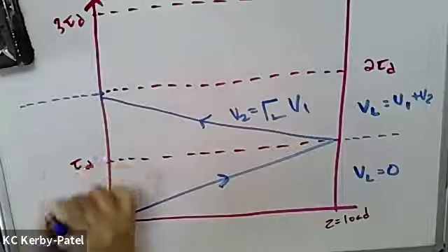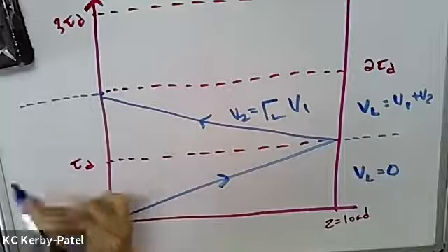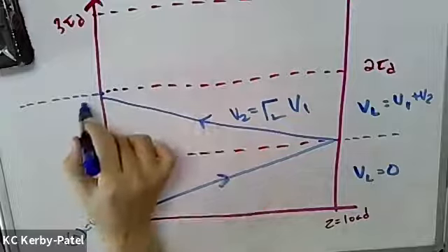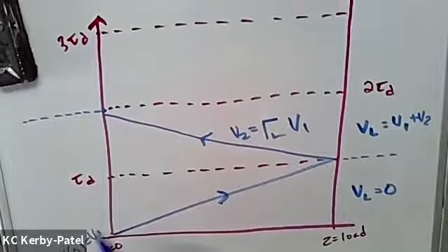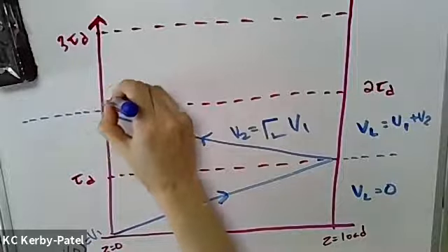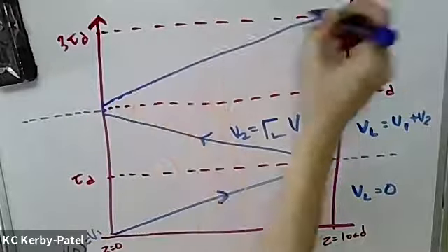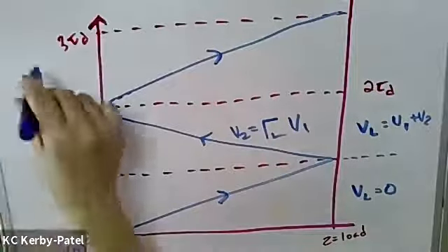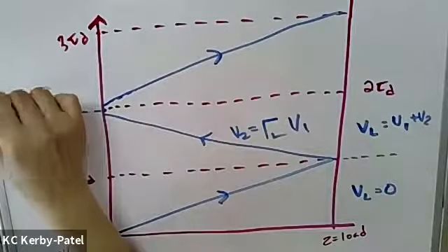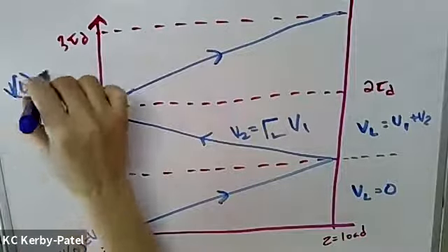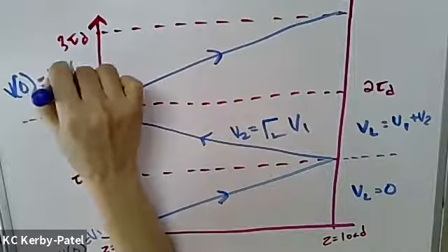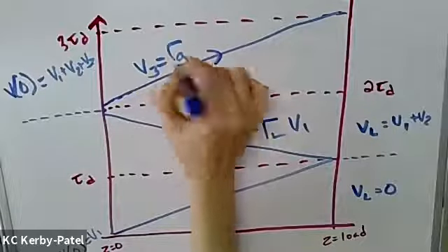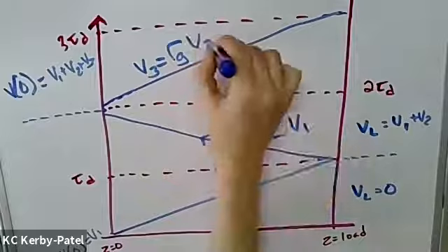The voltage here at the source, at the input to the transmission line, stays equal to V1 until we get to this point. But then this reflected wave gets all the way back. And if the generator impedance is not equal to the transmission line impedance, you can have another reflection here. So then the input voltage becomes V1 plus V2 plus V3, where V3 is the generator reflection coefficient times V2.